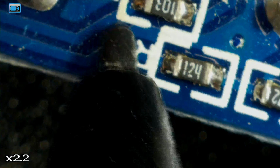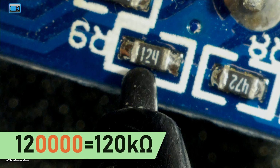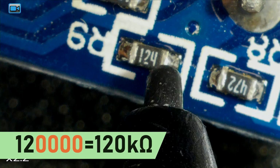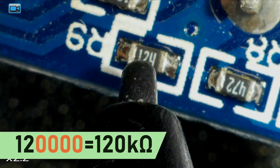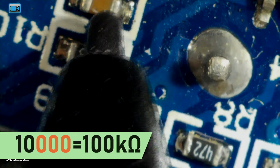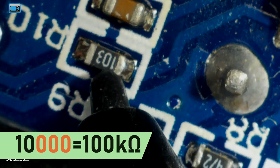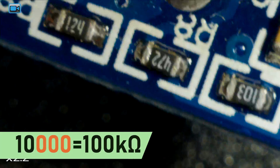Now let's have a look at some resistors under the magnifier. This says 1, 2, 4. The first one is 1, 2 is a 2, 4 means 4 zeros. So this is 120 kilo ohm. And this one is 103, which means 10,000 ohm or 10 kilo ohm.